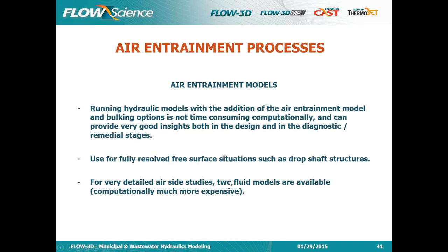Okay, so I would say that the cost of running an air entrainment model within Flow3D is actually minimal because it's a very computationally efficient model, and so there's no reason really not to run that. When you anticipate that there could be some problems, definitely just turn the module on, and this will give you some good insights as to if there's any danger.